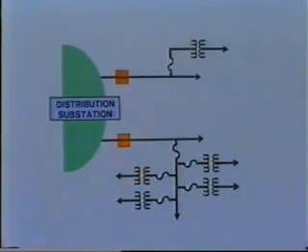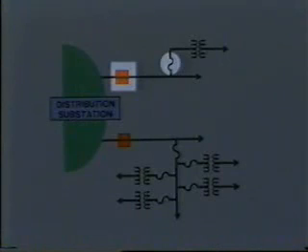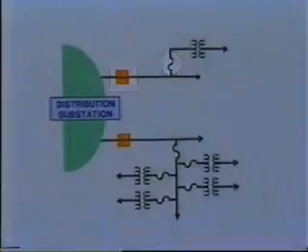Similarly, if the transformer is connected directly to the feeder, the transformer fuse and the feeder breaker protection must be coordinated. We will be talking much more about this matter of fuse coordination in a future tape. Okay, so much for the protective devices associated with distribution transformers. Now, let's look at how these single-phase transformers can be connected to Y and delta primary systems.